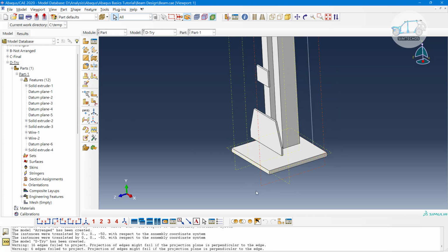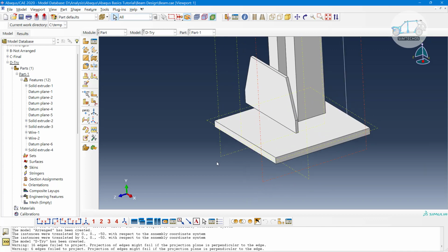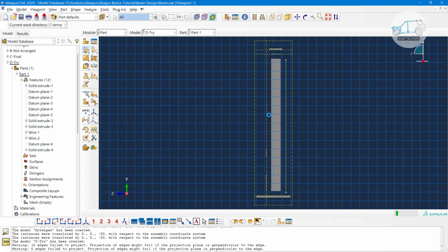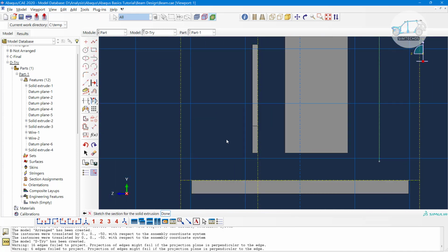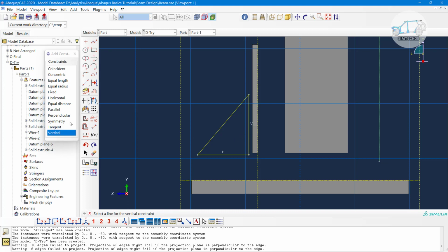The idea is we have visualization of the whole assembly. Okay. So go to the create extrude pattern, and this is my reference axis, vertical axis, and let's create. In this way the stiffener will look like. Okay, and make sure this line is vertical, then define the parameters.